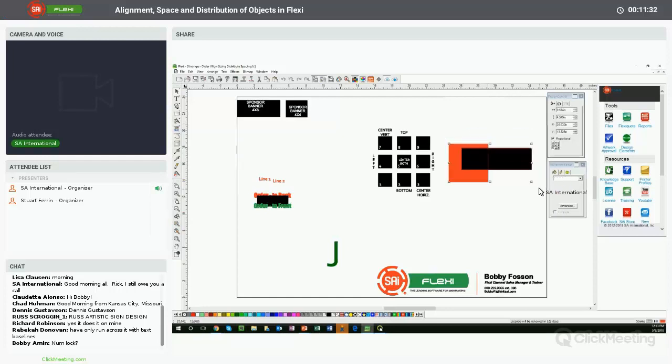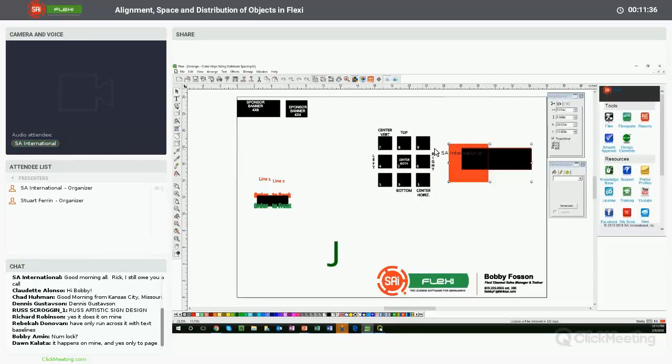And again, just to give you an example of this. Think of this as basically your shortcut keyboard here. So if I want to take these two and align them to the left, I have to hold my Control key down and hit number 4, and it should bring that to the left. If I want to bring them to the bottom, it's Control 2, and all the way around. If I want them both to be perfectly centered horizontally, left or right, Control 3 does that.